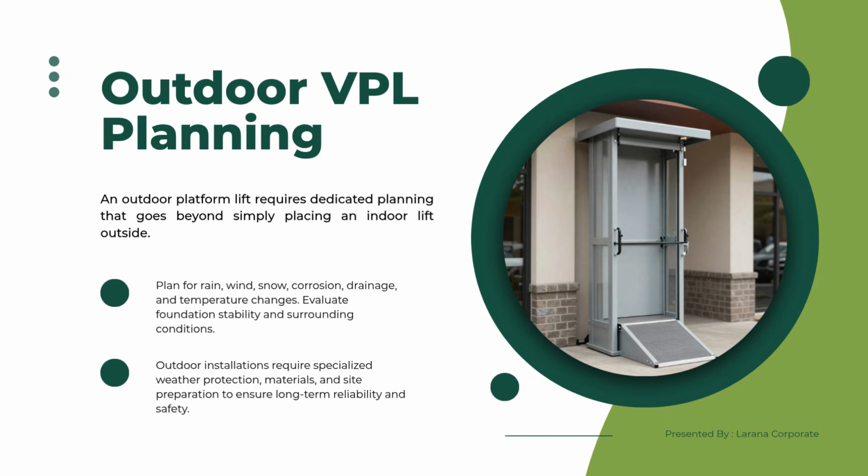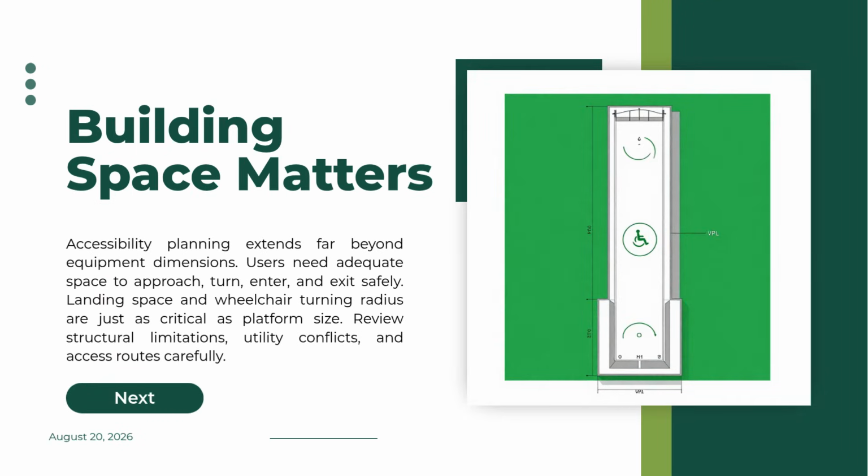7. Different buildings need different solutions. The best solution also depends on the building type. For apartment buildings, MRL elevators are often considered because accessibility, passenger capacity, and space efficiency are important. For hotels, passenger elevators or panoramic elevators may be suitable, depending on traffic volume and architectural goals.